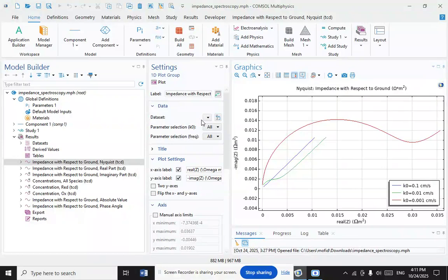For this purpose, most electrochemical analyzers are provided with suitable software enabling the simulation of the impedance data to a model circuit. Specialized equivalent circuit modeling software such as ZView and ZPlot is also available. A prerequisite for the simulation of the electrochemical impedance spectroscopy data to an equivalent electric circuit is that the validity of the data has previously been evaluated.